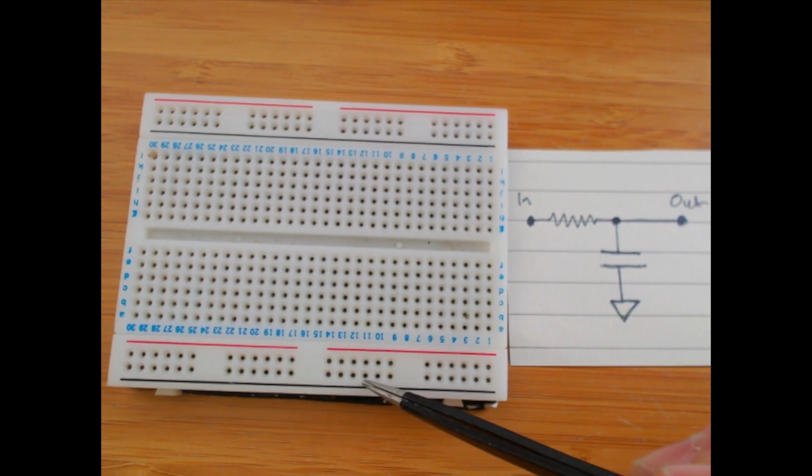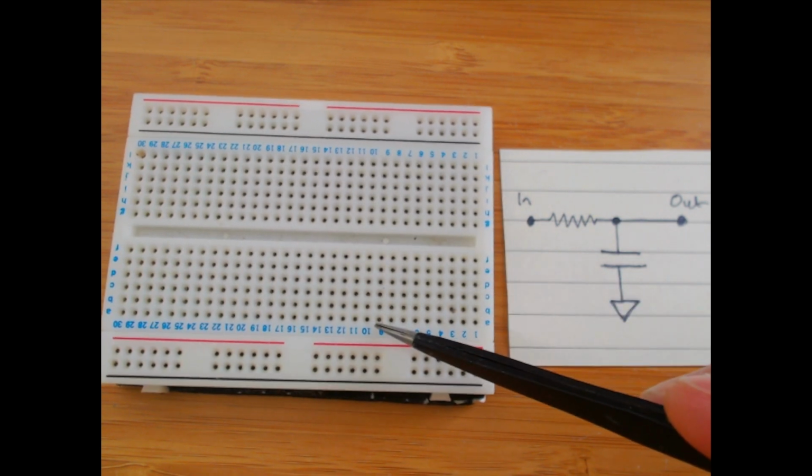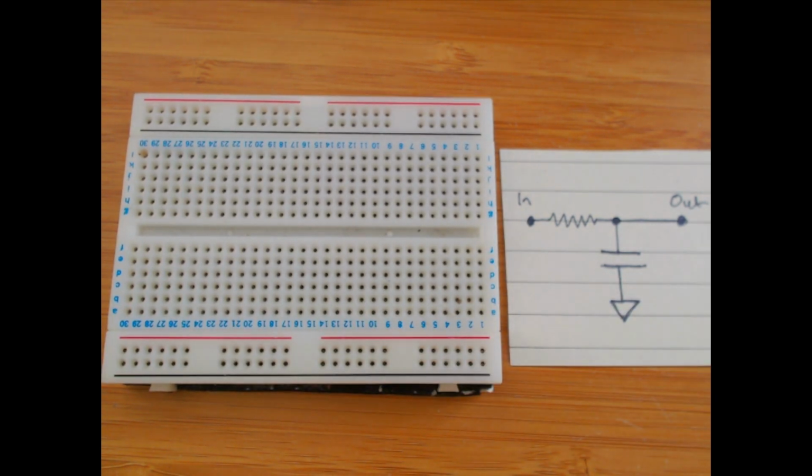But which values do you actually pick? Well, you need to calculate what kind of frequencies you want to let through. If you think about what we just did in the firmware, we set it up so that 750 times per second, so 750 hertz, we change our position. We change the duty cycle. We go to a new point. We don't need to pick up all of that noise, or that frequency, in order to display this image.